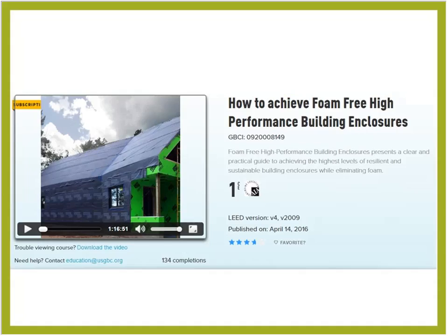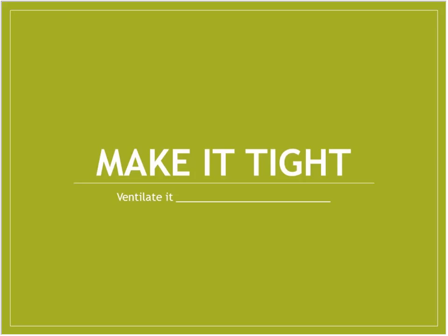Other things that are becoming more popular, as we talked about in our last module, is the idea of foam being a really great product for air sealing and resisting heat in an easy way, especially in retrofits. But there are some concerns about foam from both an indoor air quality standpoint as well as a global warming potential standpoint, and the fact that it's made out of oil. So we have a session that we've done, and there's a lot of other great work out there on this idea of doing foam-free design for new construction or retrofits, but doing it in a way that's still very energy efficient and very tight.